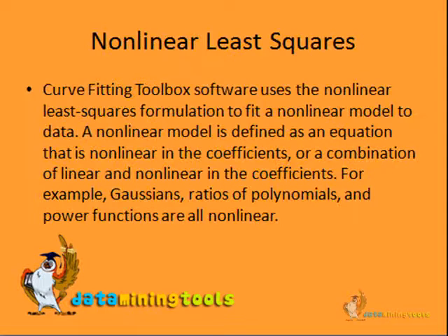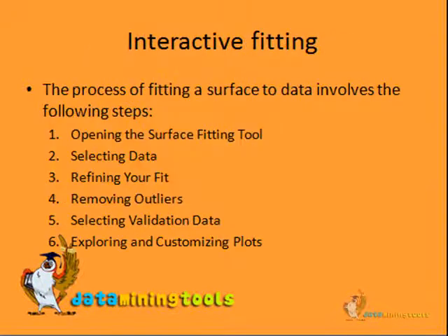Now, nonlinear least squares. Curve Fitting Toolbox software uses the nonlinear least squares formulation to fit a nonlinear model to data. A nonlinear model is defined as an equation that is nonlinear in the coefficients, or a combination of nonlinear and linear in the coefficients. For example, Gaussians, ratios of polynomials, and power functions are all nonlinear.